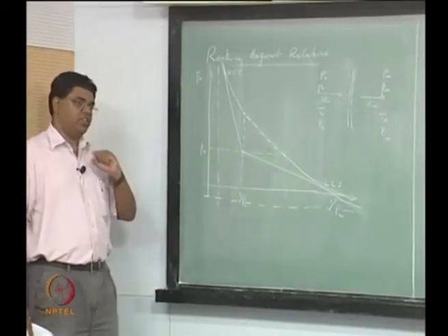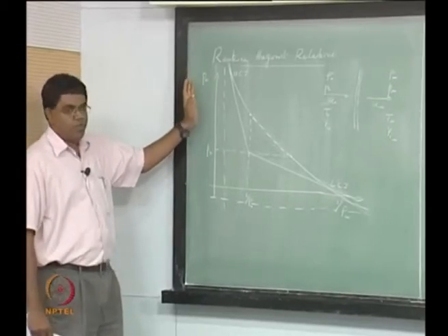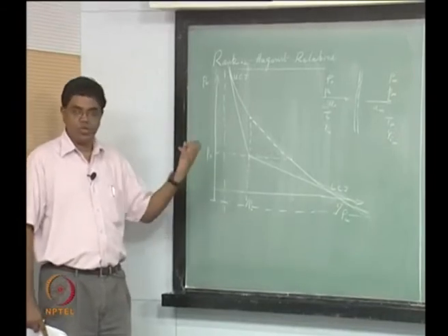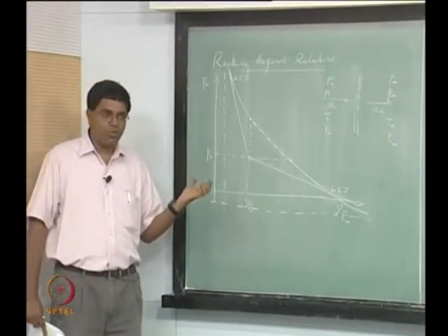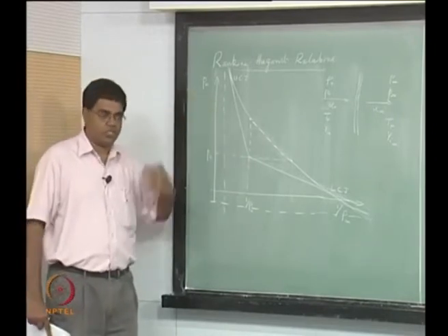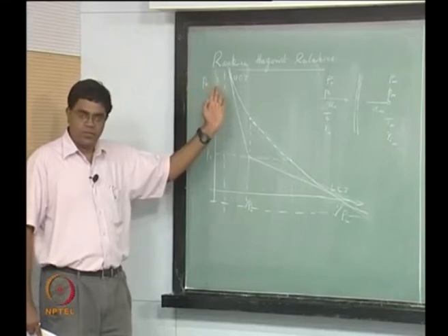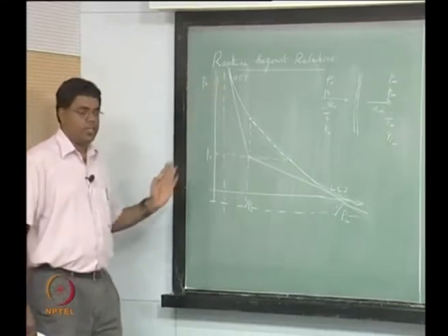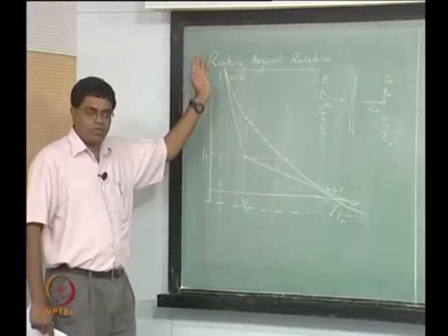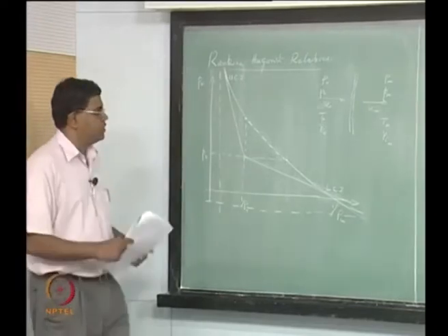So if you solve for P infinity and 1 over rho infinity together with these two equations, you get a pair that satisfies both equations, and that means that's a point where both of them intersect, right? But in addition to that, at the CJ points we also have to match the slopes, because the Rayleigh line is tangential to the Hugoniot curve, right?